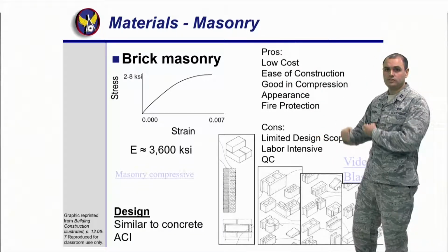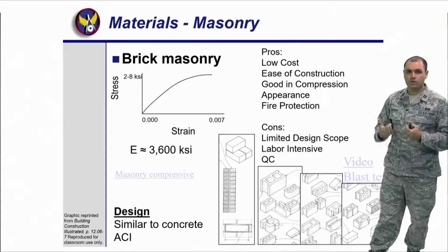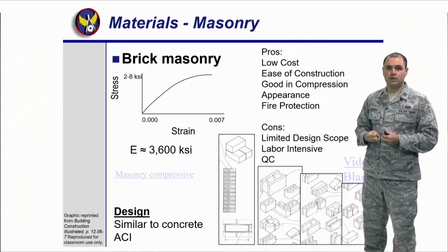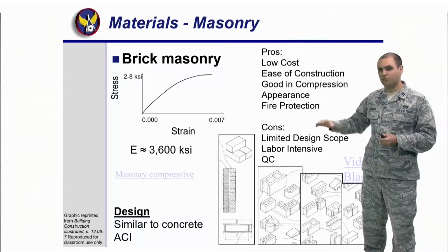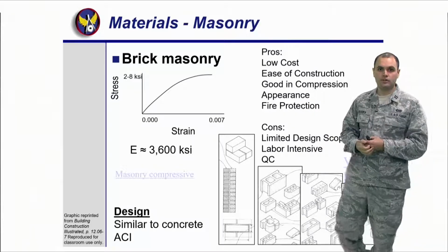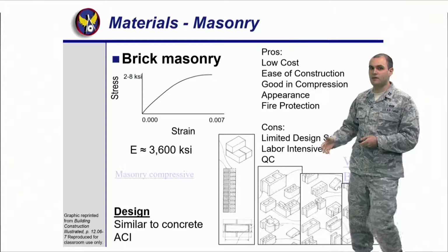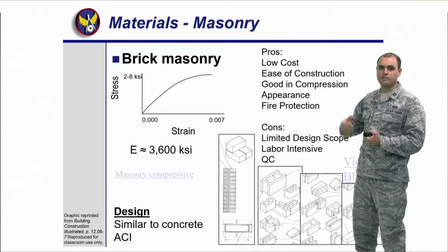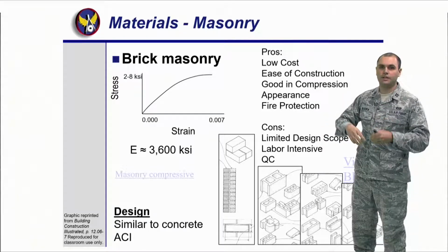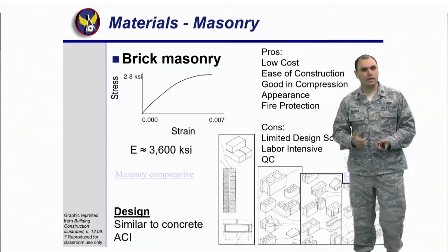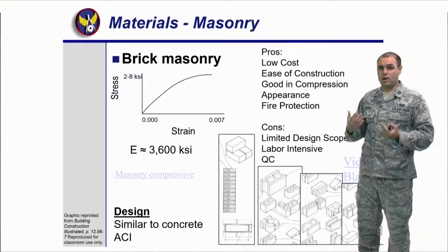However, the cons: a lot of labor intensive. I don't know about out there, but I've worked putting up brick and CMU walls, and it gets tiring. After you're 3 feet, 50 feet long, I mean, that back's going to start to hurt. You get tired. So very labor intensive, but it's very easy to construct as opposed to having to do all the formwork and pouring concrete, and then once you take the formwork out, you have to cure it and all that stuff.